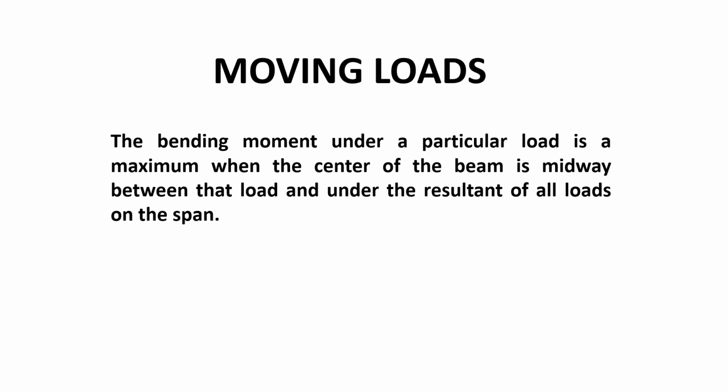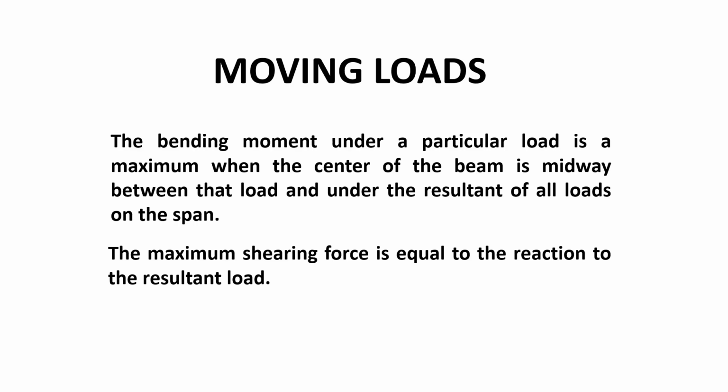First and foremost, let us talk about the moving loads. What's it all about? The bending moment under a particular load is a maximum when the center of the beam is midway between the load and under the resultant of all loads on the span. And also, the maximum shearing force is equal to the reaction to the resultant load.